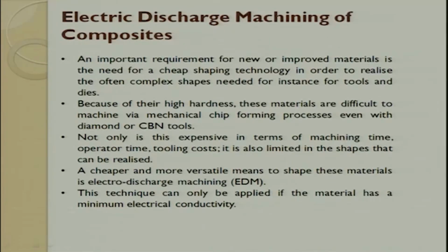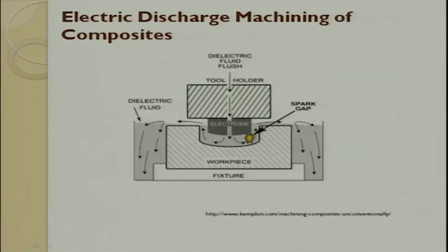Okay. So, electric discharge machining of composites is possible wherever you want to do a metal matrix composite. There has to be a metal to finish the circuit, so this is more predominant for metal matrix composite. Today people make copper based, magnesium based, iron based, aluminum based and so on.